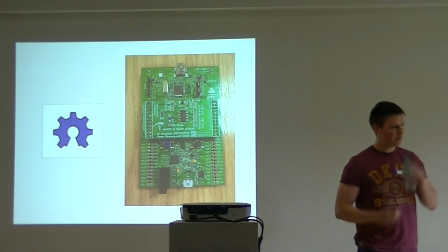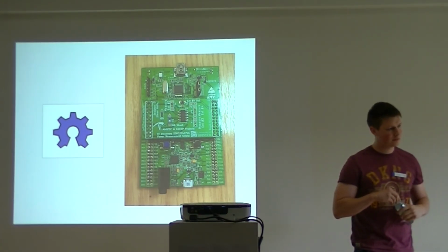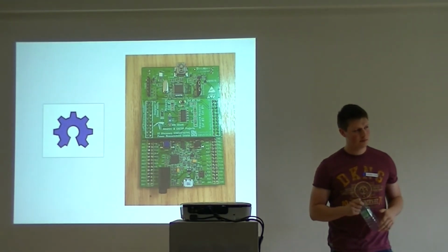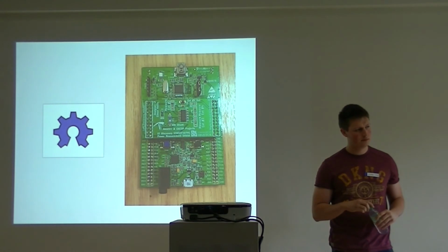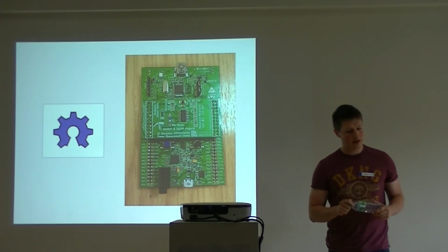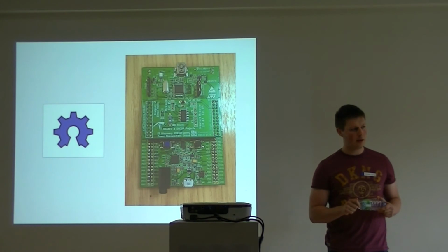What kind of total dynamic range are you talking about for measurements? So if I've got a board, for example, that is in deep sleep most of the time, pulling a few microamps, and then bursts up to say 20 odd milliamps, do you have sufficient dynamic range? It's challenging, but we can just about get that range. It depends on the shunt resistor that you choose.